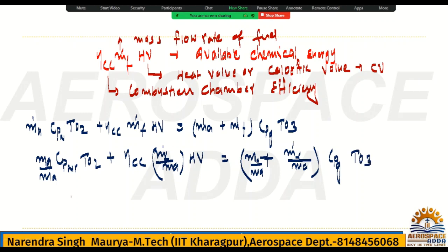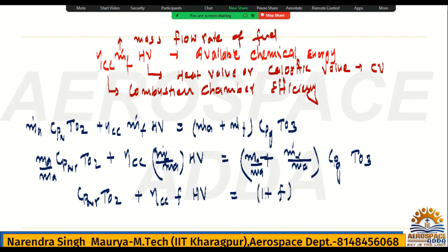So what you will get? You will get Cp of air T naught 2 plus eta cc times, what is m dot f by m dot a? It is small f, the fuel air ratio, HV, equals 1 plus small f, Cp gas, T naught 3. If you solve this equation, what you will get?